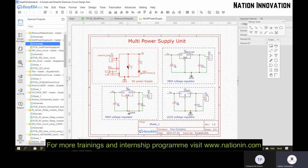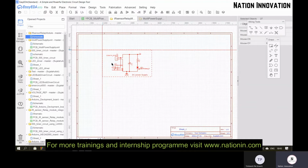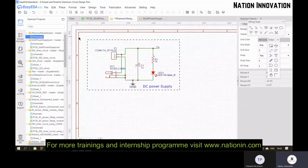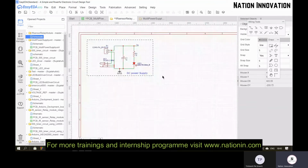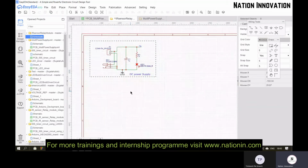Just select that unit and press Ctrl C, or right click, and there is an option called copy. Then you can go to your schematic and paste it wherever you want. This is the use of EasyEDA. No need to design the same circuit again and again; you can copy and paste here. This DC power supply will be given as input to our IR sensor as well as our relay. For the working of the relay and IR sensor, we need this DC power supply.